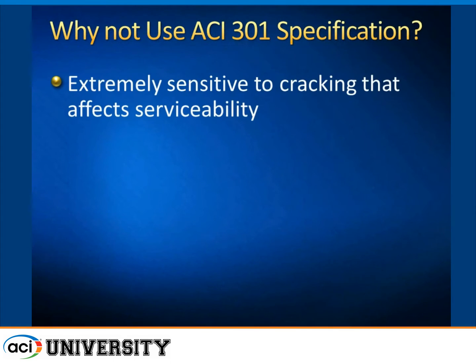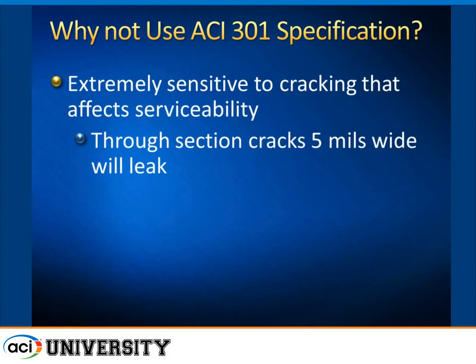We're also very sensitive to cracking. If you look at a through-wall crack, 5 mils and greater will leak. Water is very good about finding any potential way through a concrete wall section. And if you talk to contractors who have done buildings and they go and do a tank, the first tank that they do, they learn that some things are a little bit different, that you can't tolerate the wide cracks that you may be able to tolerate in a building structure.